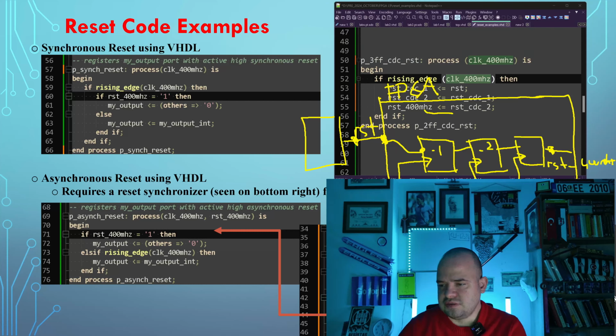And actually what you are doing, in case this reset is the external reset incoming from an IC, in case it is active, and it is an active high one, as you see, during the active time of that reset, when it is 1, the outputs of those flip-flops are also assigned to 1 asynchronously.